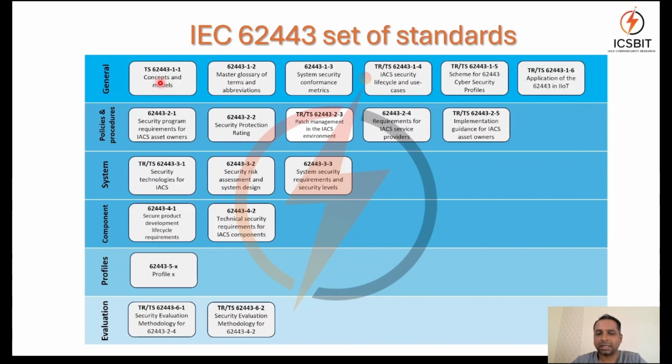When we talk about the asset owner, we are talking about a solution. I'm going to cover these basic definitions in subsequent videos. And solutions consist of many systems, right? The systems are supplied by many vendors or one vendor, that is the OEM. And a system is a group of IACS elements or discrete elements like PLCs or RTUs or HMIs or switches, routers, firewalls, you name it.